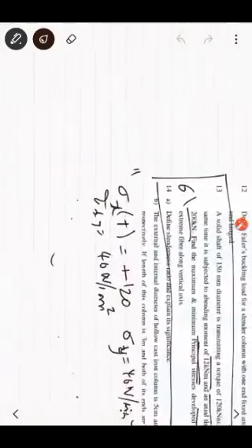Let me see whether I have solved this. Shear stress is given. I might have solved this in the classroom. The shear stress across this plane is given. The principal stress is asked: sigma 1, 2 equal to, what's the formula? Sigma x plus sigma y by 2 plus or minus 1 by 2 into square root of sigma x minus sigma y the whole square plus 4 tau xy square. The formula is correct. We substitute and get the answer.